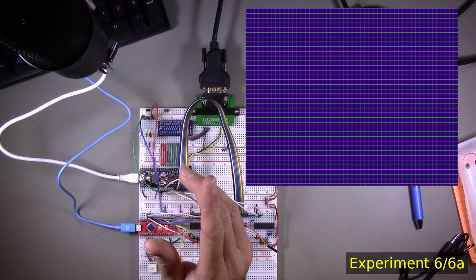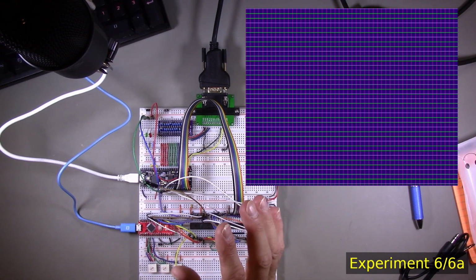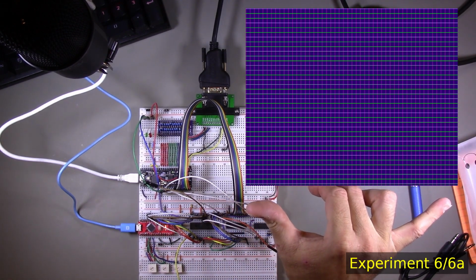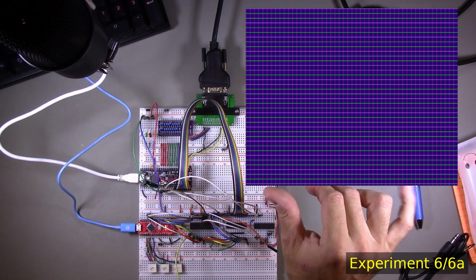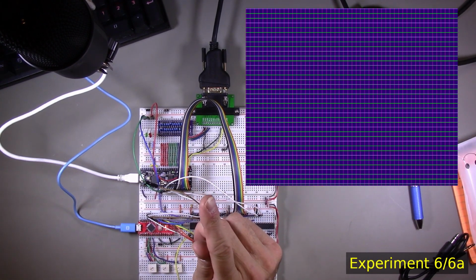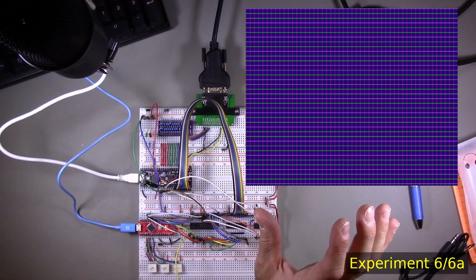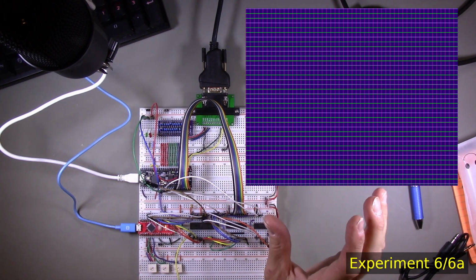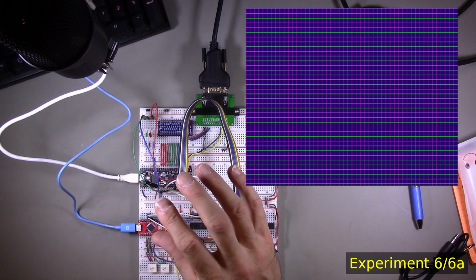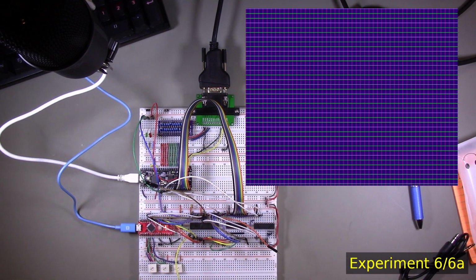I think there may still be an issue where the first column of pixels is not actually being seen, and so we're only getting maybe 799 pixels in the horizontal visible region rather than 800, but nonetheless, it was very, very close. So that meant I could take this now trustworthy horizontal and vertical sync generation and basically backport it into the version of the design that tried to display characters.